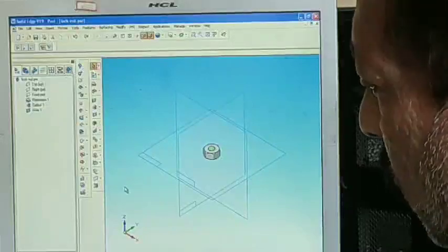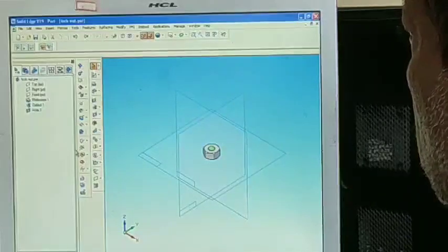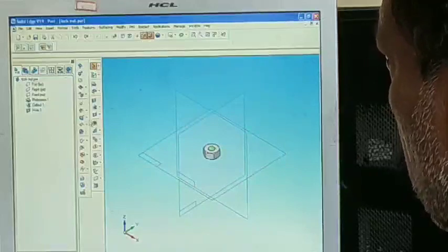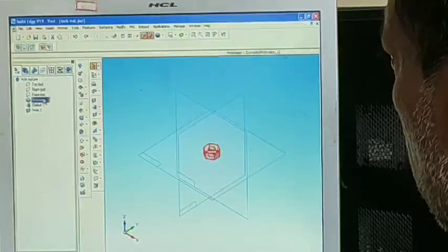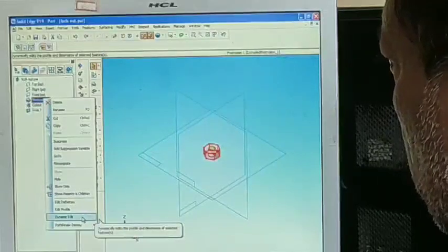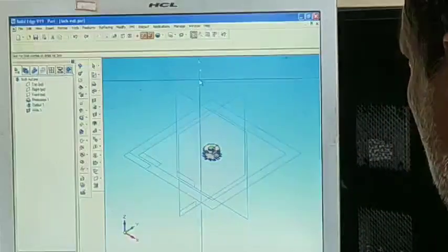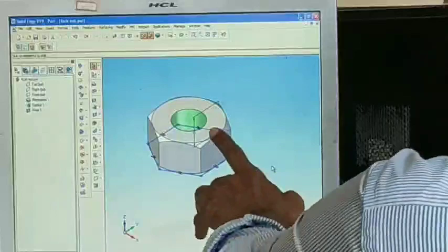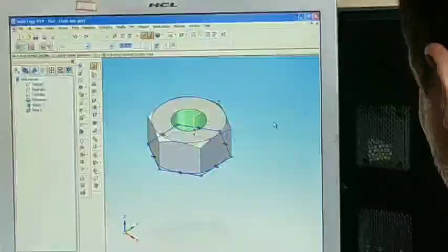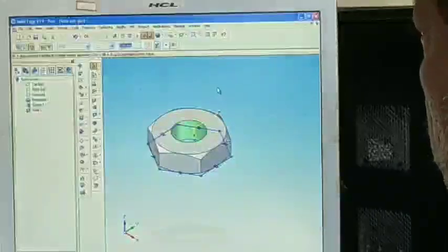So in this stroke only you can construct lock nut. This is nut. Now I am going to construct lock nut. Go to protrusion in the edge bar, right click, dynamic edit. You zoom this one. You observe here it is of 8 mm. That is nut height, 8 mm. So select this, make it as 5 mm. That is lock nut height. Now the thickness is reduced.